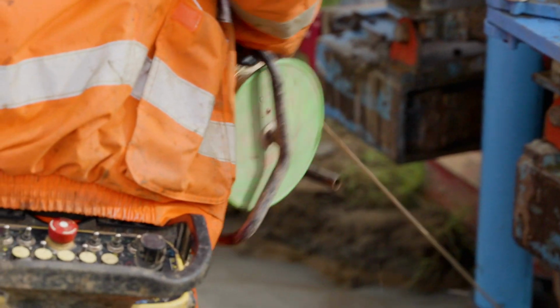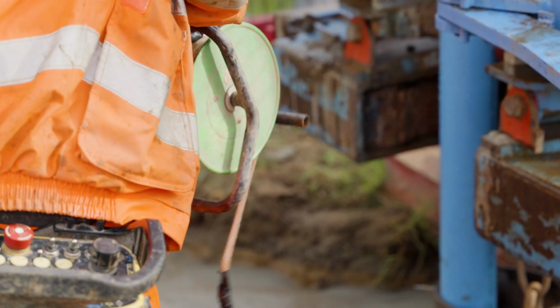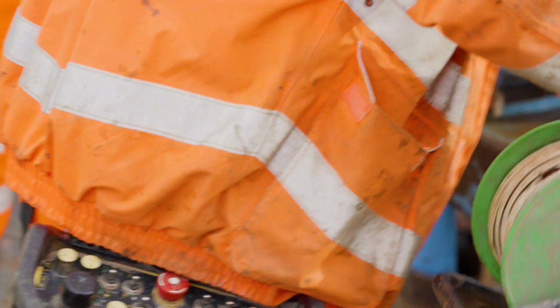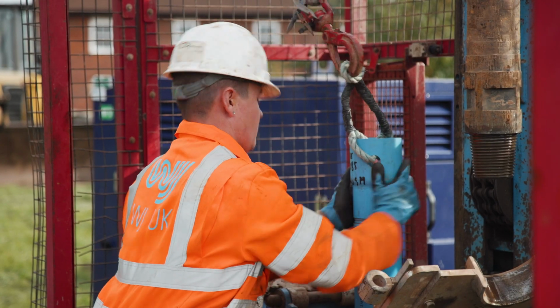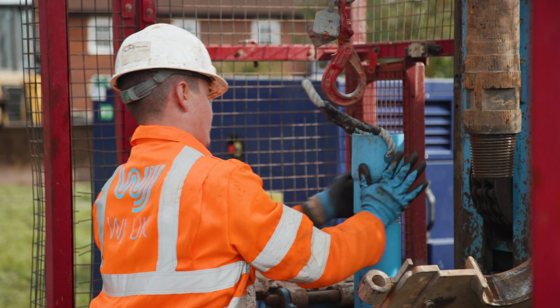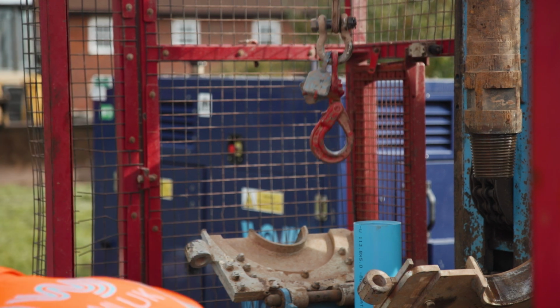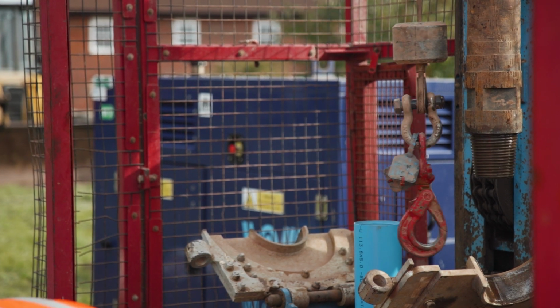Sections of the part-assembled casing and screen string are carried carefully to the rig and clamped prior to lowering. The lowest partial assembly is inserted carefully, and then other partial assemblies follow. When the total depth is reached, we measure the casing to check that it's reached the bottom. Casing shouldn't be forced down the hole. If the casing isn't installed to the correct depth, it may need to be removed and the borehole reamed.